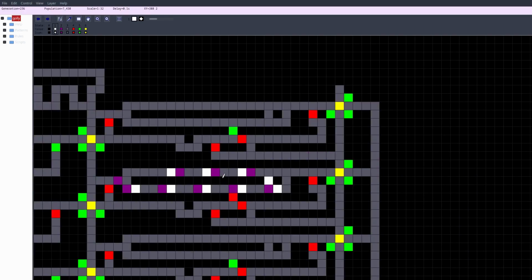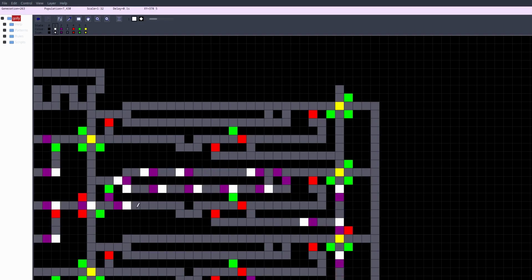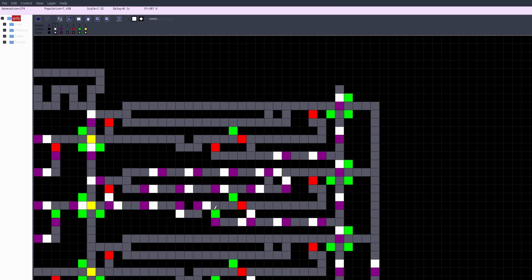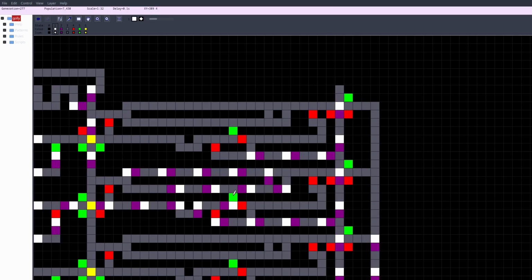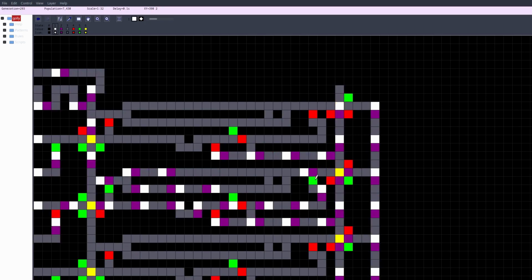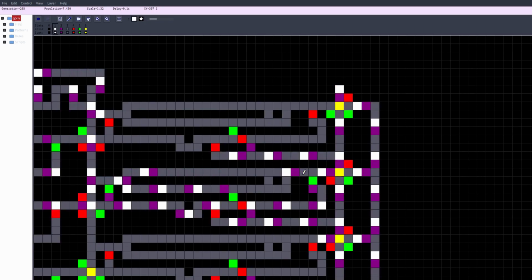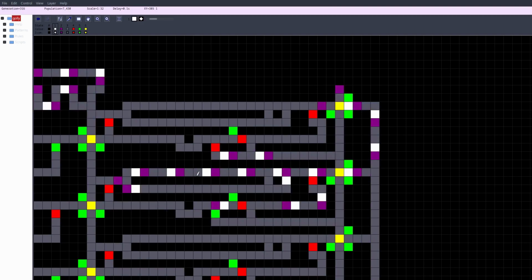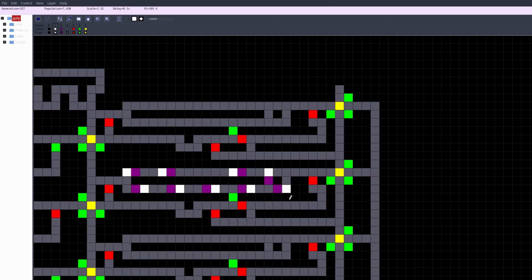Writing is a little bit more complicated. This line is the write signal, and this line is the data to write. The select signal here is ANDed with the write signal. This is then fed into an AND NOT gate, which deletes the signals already in the loop. Same signal is sent along here into an AND gate with the data to be written, so the data only enters the register that has been selected.